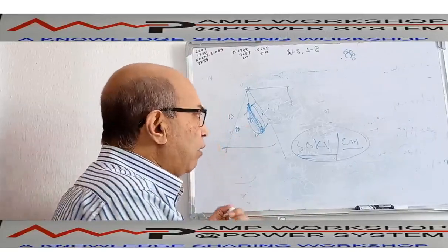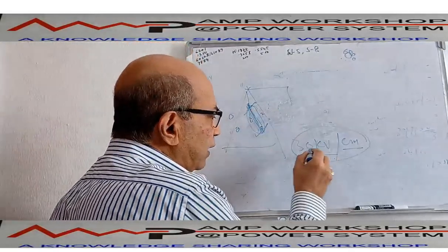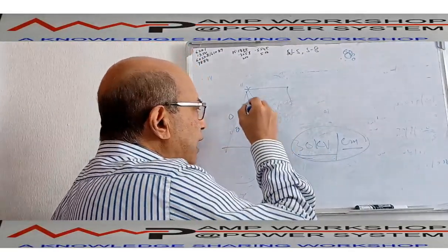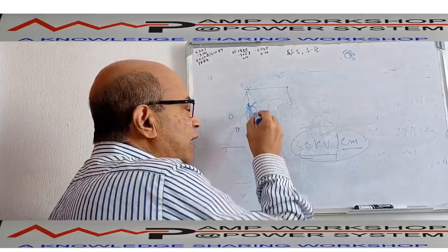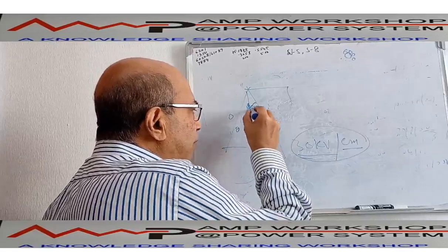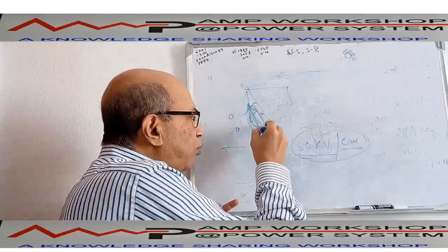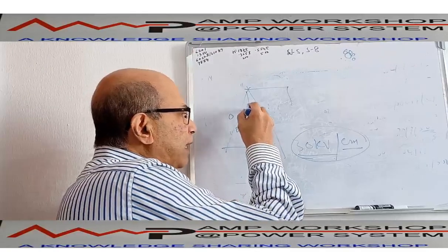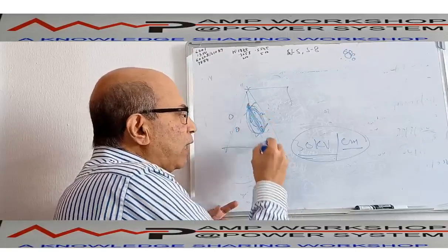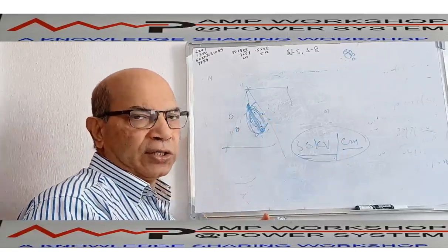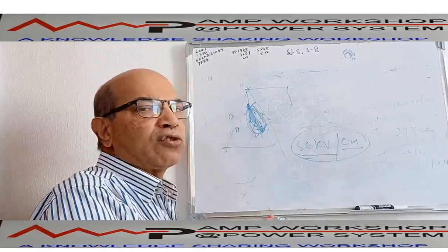What is happening during this time? If the voltage goes up or the air density drops down, and there is humidity in the air, then some of the air particles will get ionized, and due to the ionization they form a plasma. Due to the plasma there will be conduction from one phase to another phase, and that plasma helps to discharge this corona.